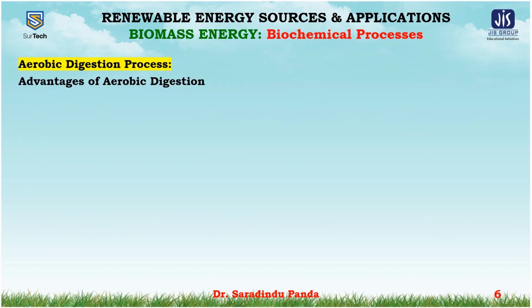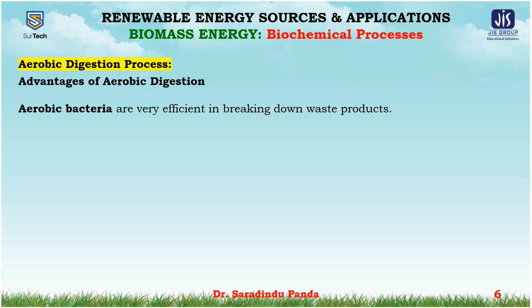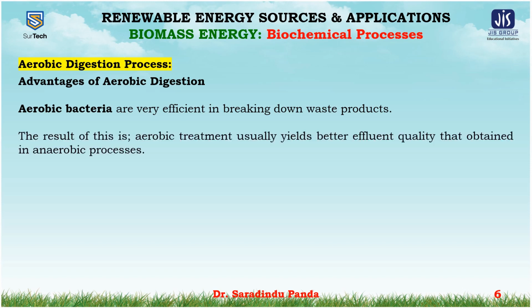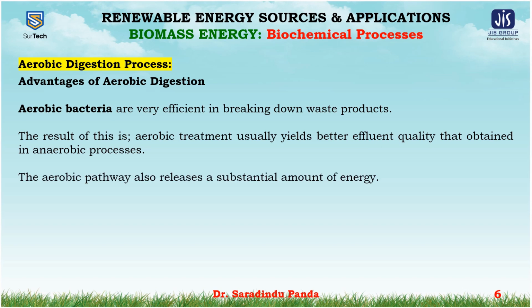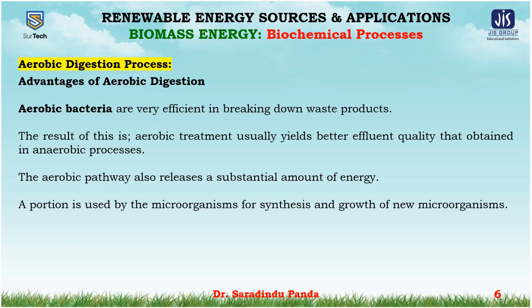The advantage of aerobic digestion: the aerobic bacteria are very efficient in breaking down the waste products. The result of this is that aerobic treatment usually yields better effluent quality than that obtained in the anaerobic process. The aerobic pathway also releases a substantial amount of energy. A portion is used by the microorganisms for synthesis and growth of new microorganisms.